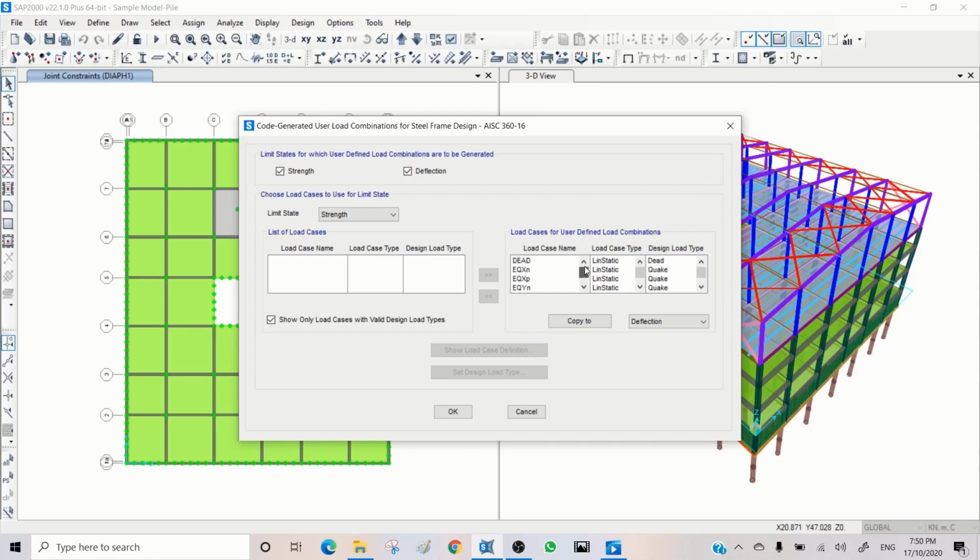You need to see. So you define dead load for self-weight, and superimposed dead load and wall load. That means they shouldn't be here, but you can see superimposed dead load. You need to move it back here. That means I'm not using this load case. And then self-weight and wall. You can press Control and select multiple load cases and then put them here.